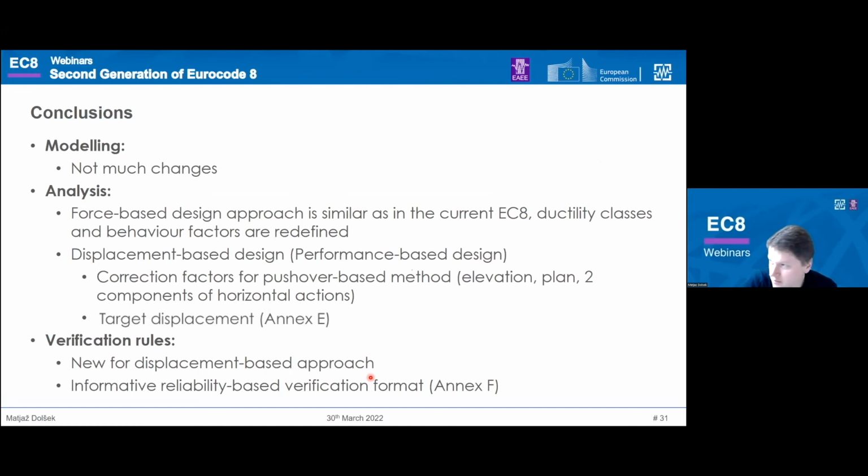To conclude, for the modeling part, there is not much changing in this Eurocode 8 Part 1 in respect to the current version, but there are, let's say, novelties in the other relevant parts of the code about the modeling too. For the analysis, the force-based design approach is very similar to the current code. Ductility classes and behavior factors are redefined.